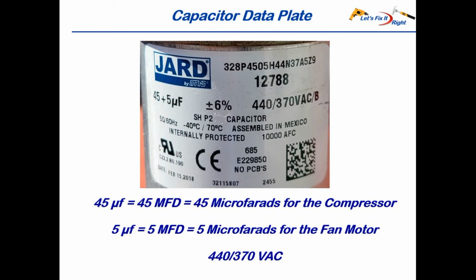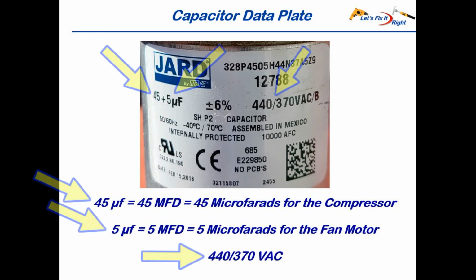This is the blow-up picture of my capacitor's data plate. This is its part number. If you can get the same part number, that's good, but it's not critical that your replacement has the same part number. In fact, in many cases, you will not be able to get a replacement with that part number. However, it's critical that these three numbers on your replacement match these numbers on your old capacitor.